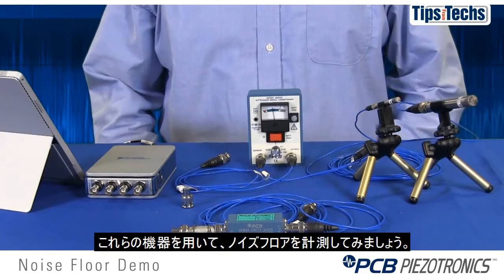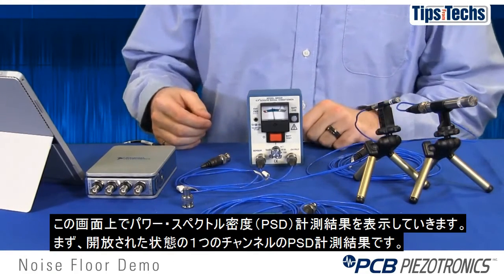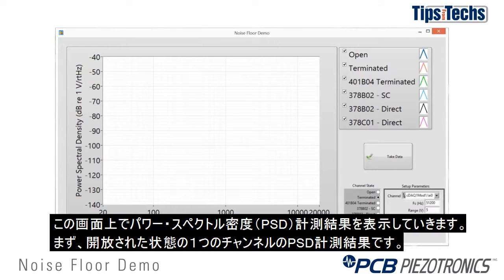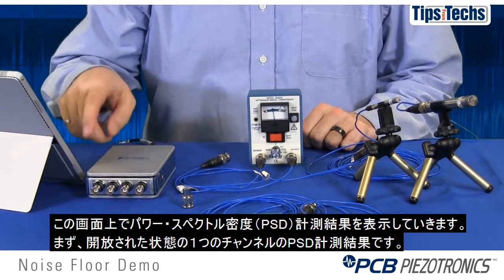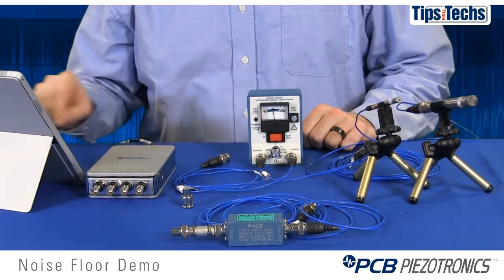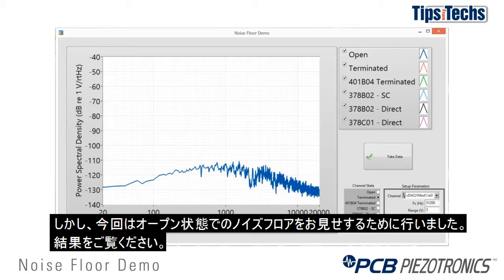So now we'll demonstrate the system noise floor with several different components. What you see on the screen is the power spectral density measurement from all the measurements we're going to make. We'll start out with just an open measurement of the power spectral density of one of these channels. Now, I don't ever recommend taking this measurement because these channels are meant to be terminated with a resistance. But just to give you an idea of what the noise floor looks like when they're open, you can see it on the plot here.